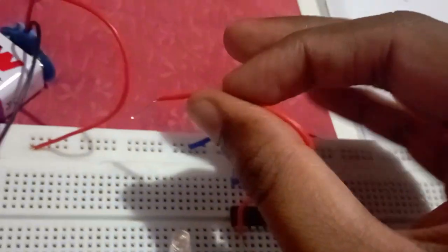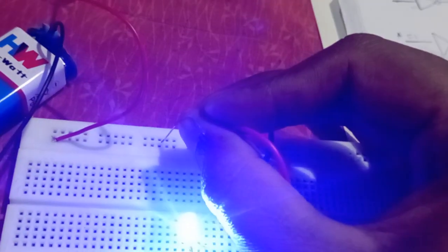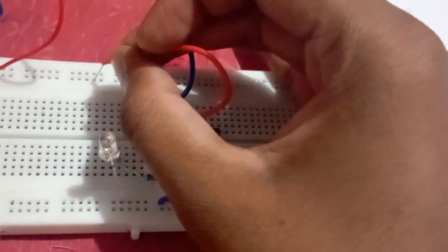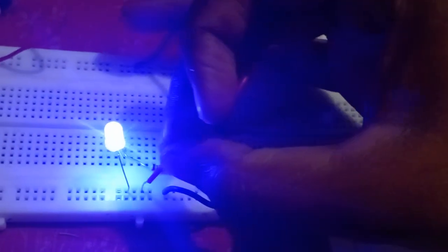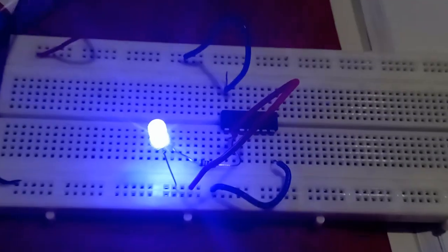So I will remove it from the ground, and now I am going to connect it to volts, that is this side, battery side, positive side. When I give it here, the LED must go off. See, the LED has gone off, so it is verified. So I remove it. Now you can see it, when I give ground, the LED must be on. That is this side. So the LED is on. So this is the verification of the NOT gate.